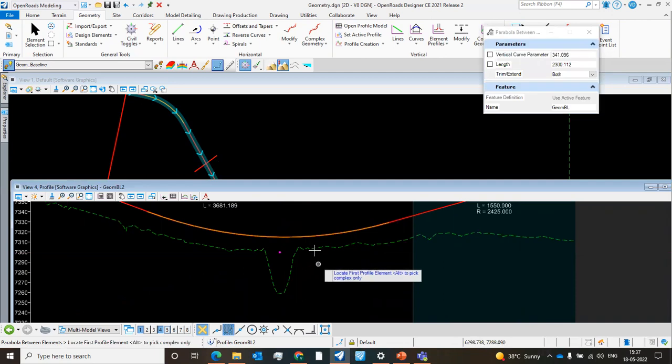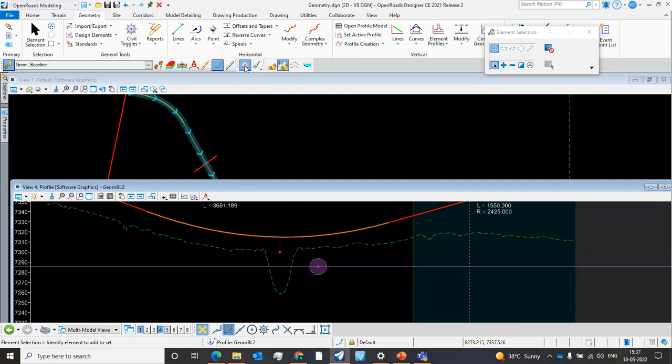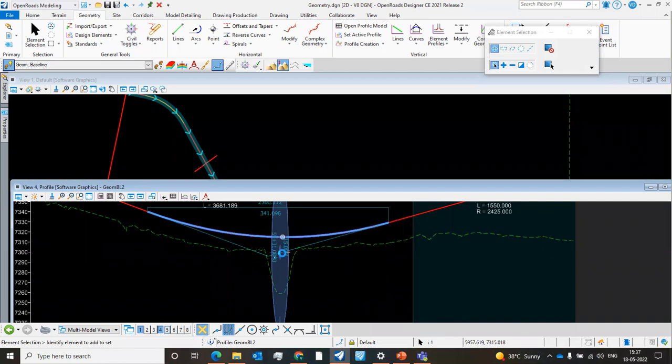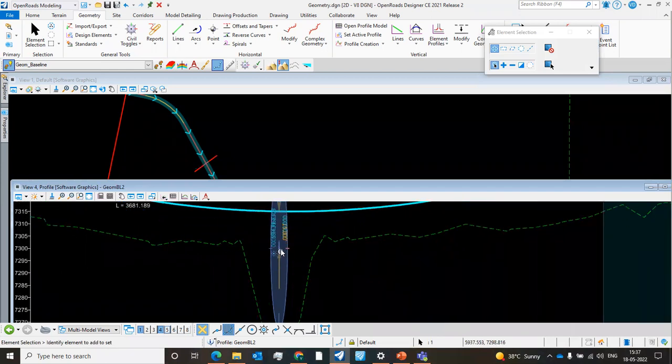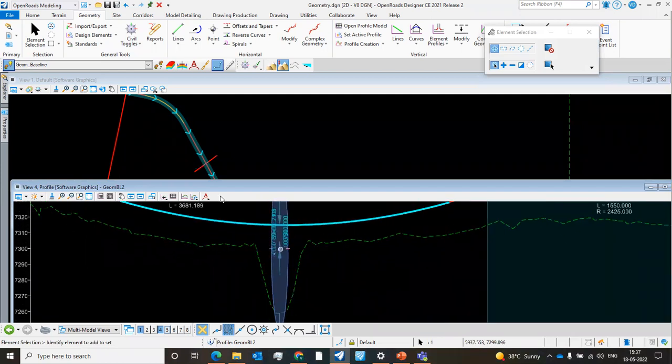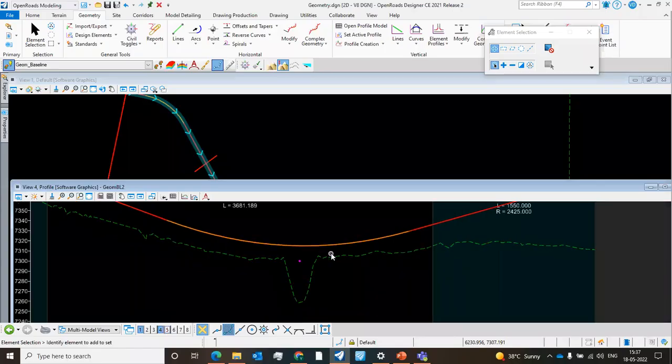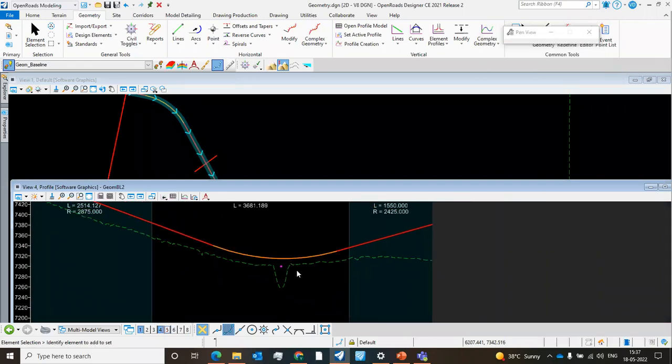Now you can see I'll toggle off the civil Accudraw. Now you can see this curve is having a relationship with that particular point, which is the elevation of this culvert or this line, and maintaining a depth of 15-meter. So now, as you can see, the relationship has been established.